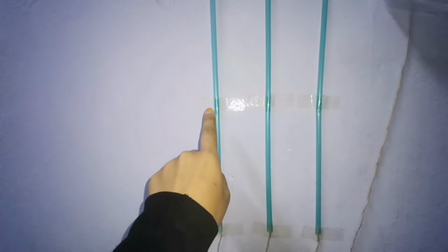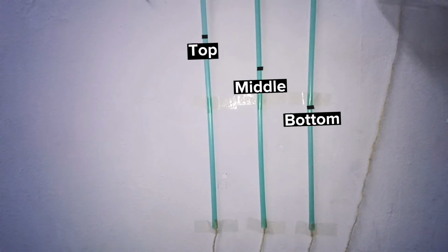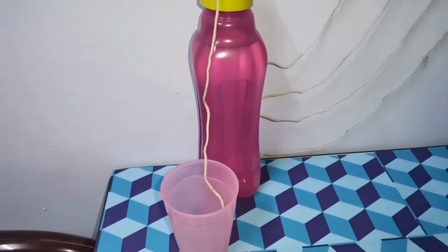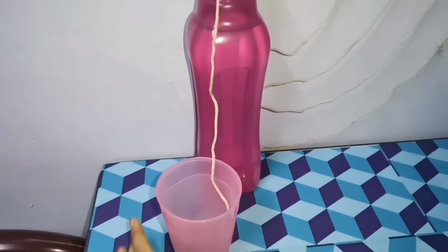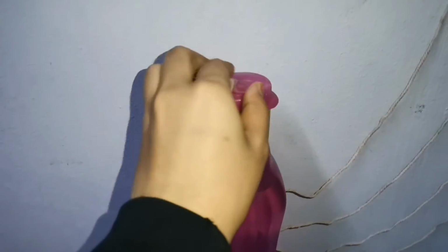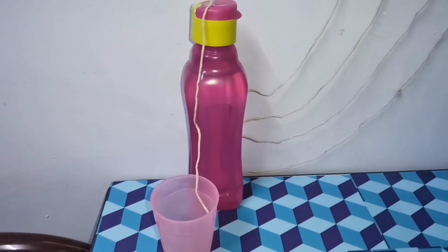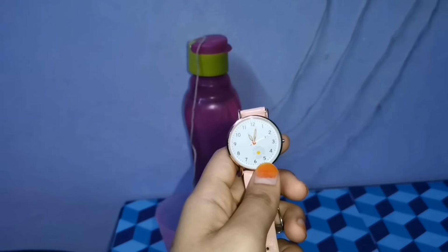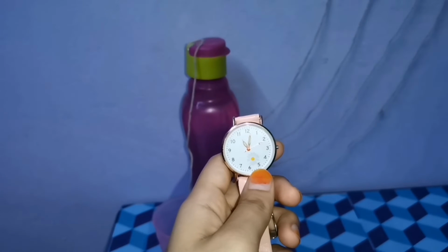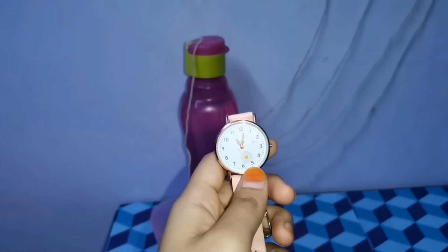And don't forget to measure the height difference between the top standpipe to middle and middle to the bottom. Prepare the empty measuring cylinder to run the test. Open the valve that connects the permeometer to the measuring cylinder. By using the stopwatch, take the time for 500 ml, 700 ml, and 1000 ml and record the data.